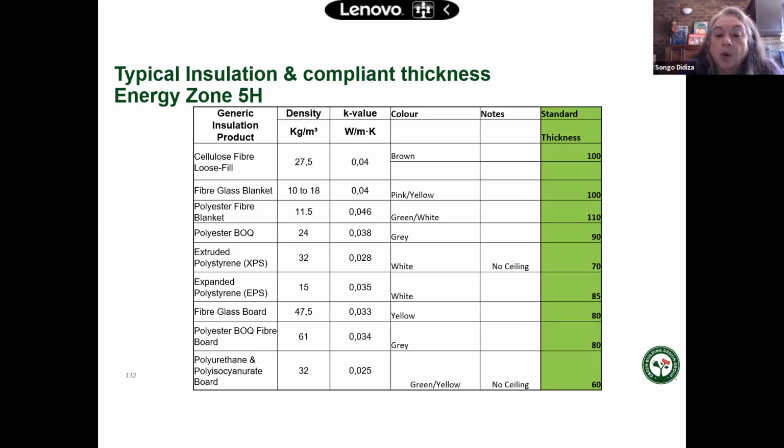So the actual board, the XPS, is a tongue and groove sealing system. So now, if you take out the plasterboard sealing, you're taking out an R value of 0.06. If you take anything out of that system, you have to add that R value back into your system R value.